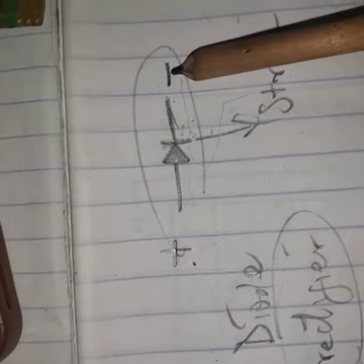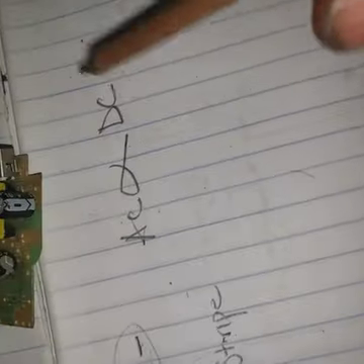A diode is used to make a rectifier. What is a rectifier? A rectifier is actually a circuit. Some you might just see like this, or others are enclosed, but it's always a circuit that converts alternating current, AC, to DC using these diodes. So with the help of the diode, a rectifier converts AC to DC.